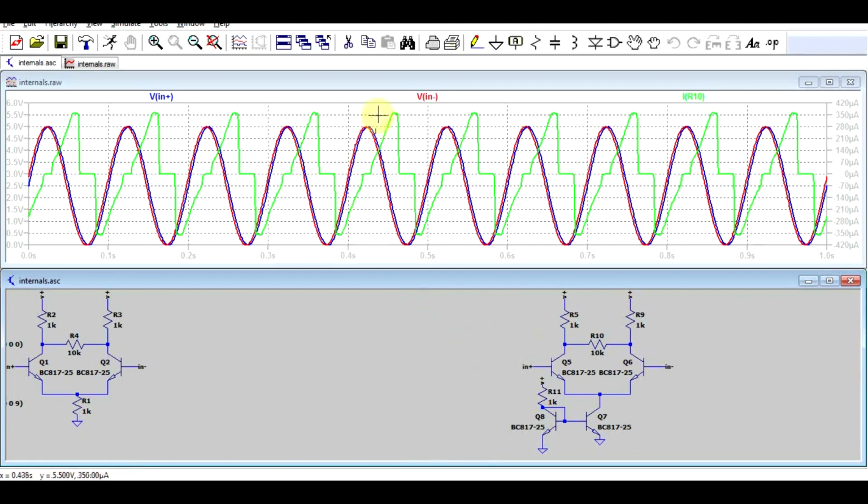Now, what happens if we go to very high input voltages? The base emitter voltage always stays roughly the same, so if we have 5 volts on the input, then the emitter will be roughly 0.6 volts below that, so 4.4, not a problem. The low transistor can handle this without any issue, so it can sink currents through it at voltages even higher than 4.4, at 5, at 6, at 10, doesn't matter. So our high voltage limitation is not coming from these three transistors. The high voltage limitations comes from something else.